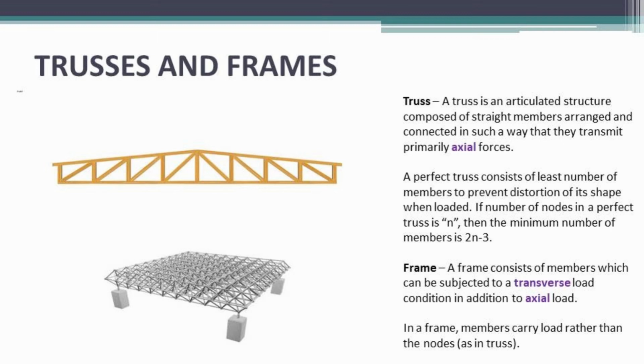Now, if load is applied at a point other than a joint, the member is subjected to bending, and in such a case, the force in the member is not purely axial. That's why transverse loading is also present. To find the forces in the members that are getting subjected to bending, the equilibrium of each member is considered separately by constructing what? Free body diagrams.